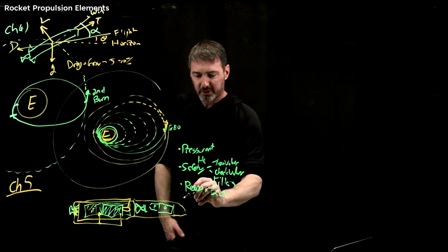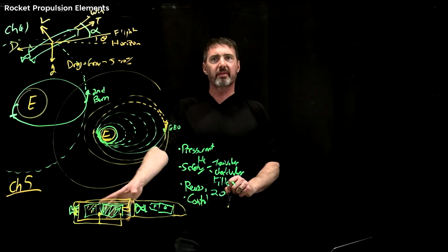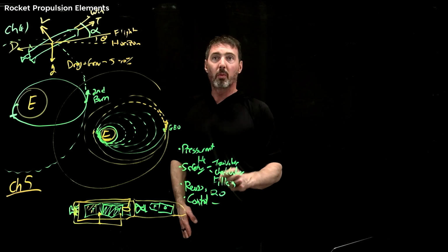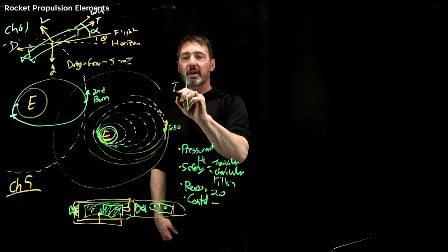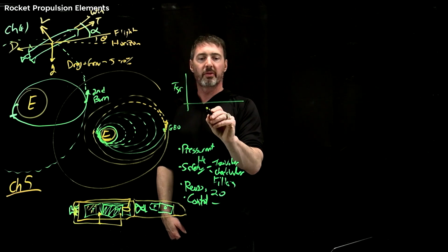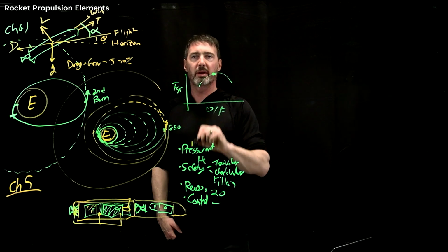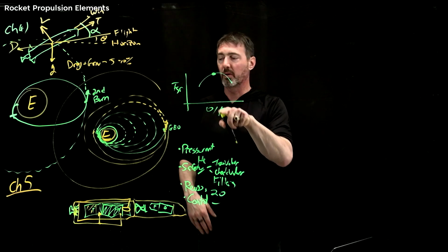Okay, there's control. A couple of different things. This diagram's getting crazy, so I'll just mention it by words. But one is your performance. So here's ISP, and I'll draw it versus O to F. Maybe you've got some curve like that, and you want this very specific O to F. That's what you've designed it for. That's what you do a couple of tweaks.